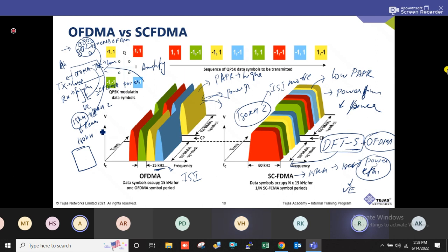The opposite is SC-FDMA. In SC-FDMA, the transmitter is simple and the receiver is complex. So both complexities are given to the eNodeB itself. The eNodeB can take that complexity because it has enough bandwidth of power and even receiver sensitivity to take all this data. Okay. So I have given you this analogy so that you can clearly understand the complexities in OFDMA and SC-FDMA.